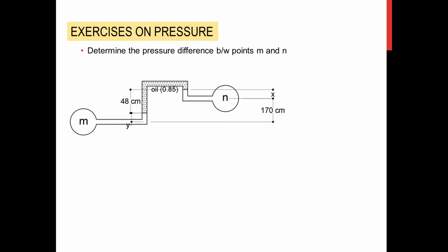On our first two examples on manometer, we have an open manometer wherein we can compute directly for the pressure, but this time we cannot derive the particular pressure at M and N, but this is more on the difference of pressure between M and N. Again, that is because there is no open surface here. That is why this manometer is called differential manometer.